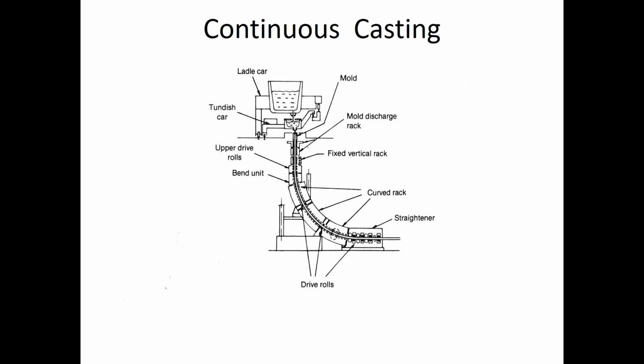But in any event, you come down to, as the metal is still warm and still formable, into a horizontal feed, outfeed, or takeout, and a straightener to make sure that everything is straight. It's fed out onto a table or a run-out area, and in many cases, this is cut to length.